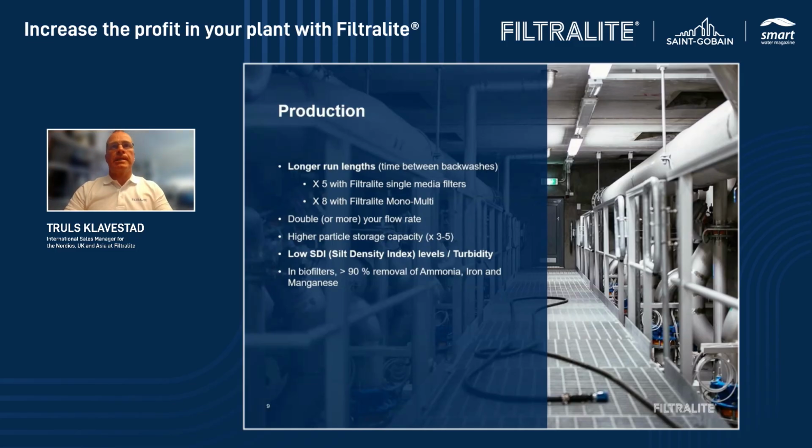If you do the comparison with single media sand, I know that is an unfair comparison, single media compared to dual media, what we call Filtralite monomulti. Filtralite monomulti is a dual media filter where we have high density filter material in the bottom and a lighter material on top. Then, instead of backwashing once a day, we can backwash every 8 days.